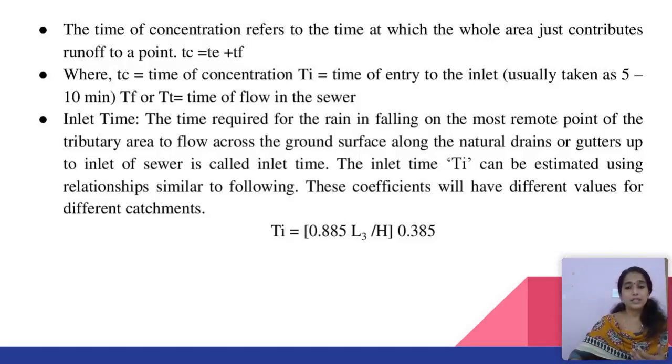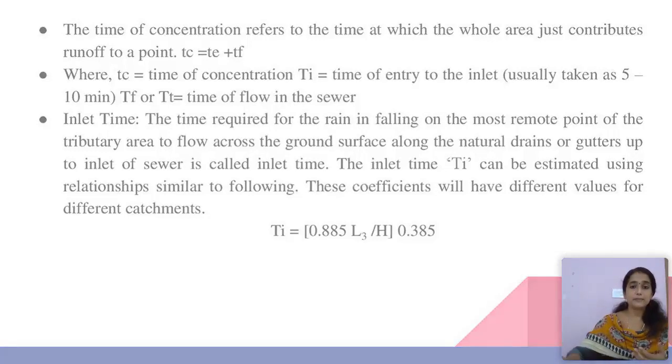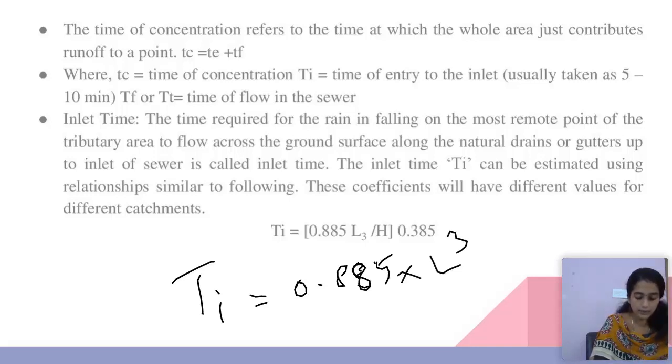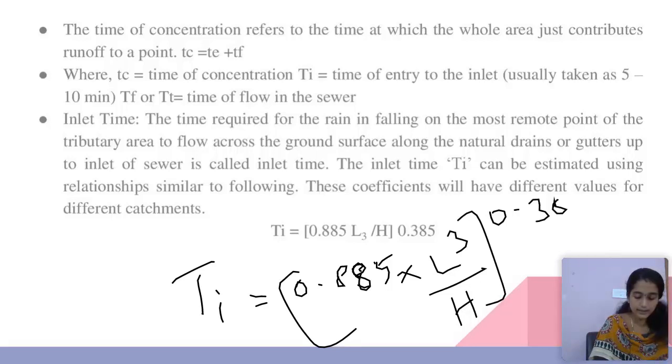There is a correction in this equation, please note it down. That is, TI is equal to 0.885 into L cube divided by H, raised to 0.385.